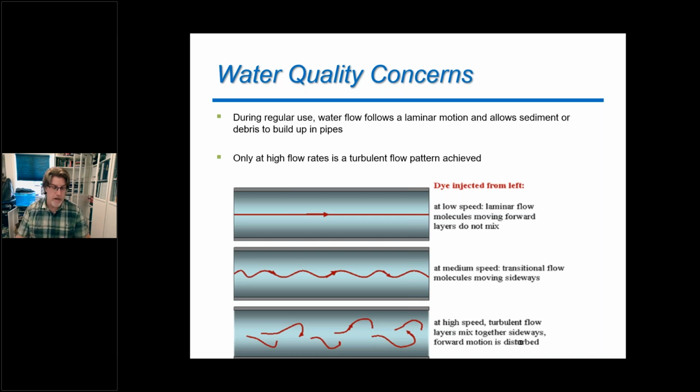They're going to get a chance, if we get high enough, to maybe tear off any biofilm that might be growing on the pipe, and hopefully carrying that out to our discharge point, right? So that's really our objective, is to create as much turbulence as possible within the pipes in our distribution system so that we can pick up and discharge that debris that has accumulated over the year.